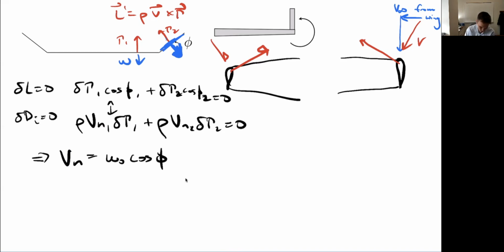And remember, it's inducing a velocity downward on itself, right? So if I looked at, just for example, this bound vortex, it's inducing a velocity downward. Actually, all of these are, right? Are inducing a downward velocity on the wing on itself. So again, take that wing, rotate it 90 degrees. Now it's a winglet. So what direction is the winglet inducing on itself? It's downward still, but now that's left to right.